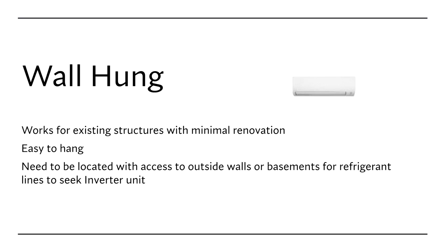The easy part is they're relatively easy to hang. It's almost like hanging a picture. You want to get them level, and you need to have enough anchor points to hold it up. But they're not really heavy. One person can lift it up in place and get it hung up, and it doesn't require a lot of extra help to do it. The location of these is usually placed someplace where they can either have immediate access to the outside wall of the house or to an inside wall that can be chased down to the basement, and then out the basement out to the inverter unit.